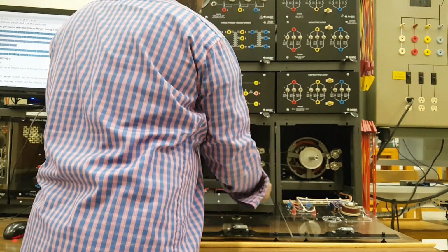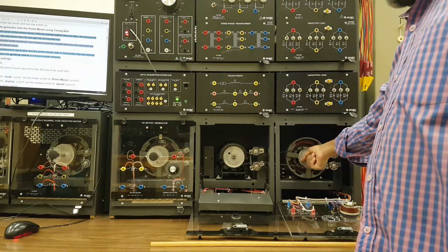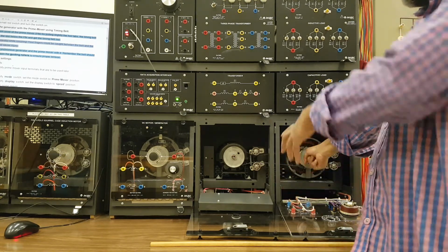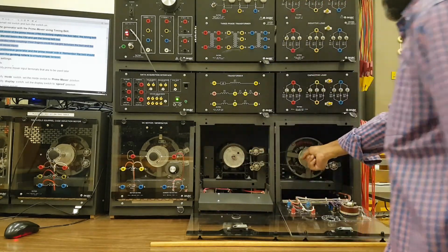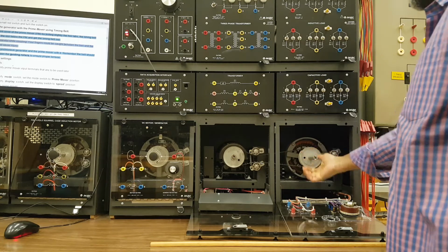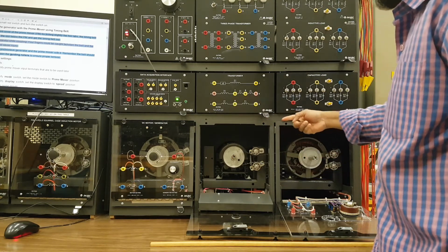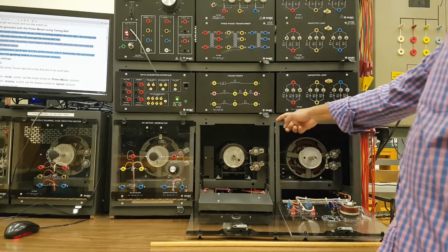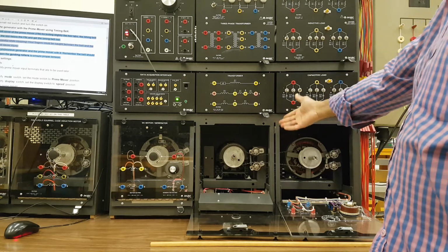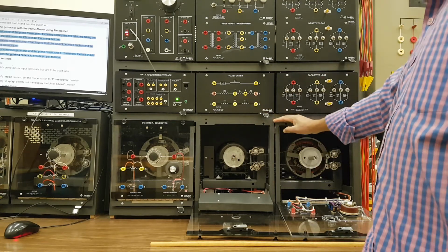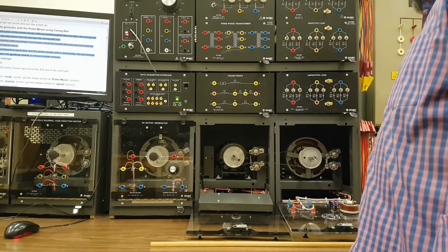Once it's gone inside, I try to turn it and see if they are aligned properly or not. If there is misalignment, the belt will come out. That is an indication of misalignment. You can also see these two frames are matching. If you are physically here, you would see they are in line. I don't know whether you are able to see it with the camera or not, but you can also make sure of the alignment with the alignment of the frames.